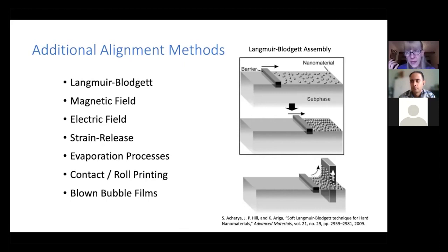And in that drawing process, we could have chosen some oils that would have started to have some lighter volatile components being driven off. The maximum temperatures in that particular drawing process were probably right around 160 to 170 degrees Celsius. So you've got to be sure that you're choosing something that's not going to start to volatilize.